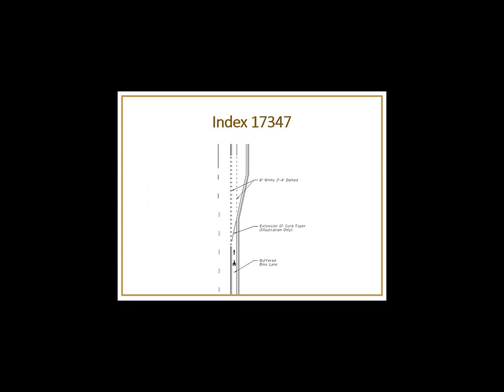With a 7-foot lane, we ended up losing a lot of the area that cars need to maneuver. So the 2-4 dotted lines represent really the conflict zone where cars are trying to move into the right turn lane and where the bicyclists are either moving into the right turn lane or moving into the keyhole lane. So this is a conflict area.